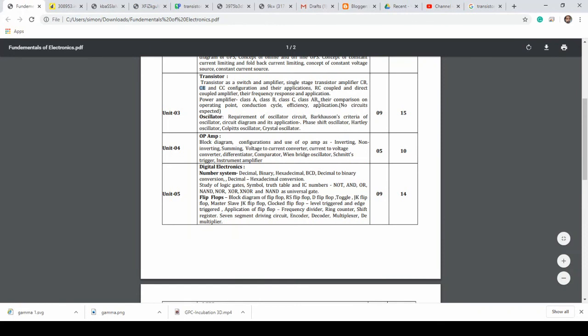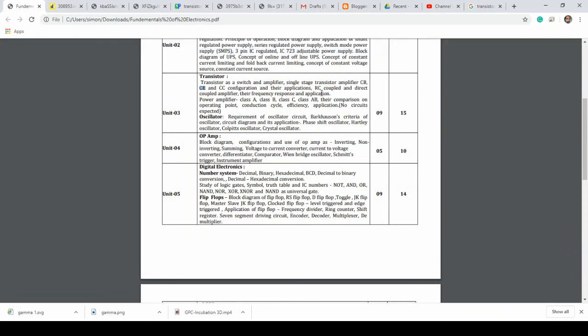And the next would be the frequency response. We're talking about the frequency response. At what frequency will the amplifier be able to give me desirable gain or desirable amplification in reference to dB? And we talked about the wide range of audio between 20 and 20,000 hertz. And for radio frequencies, for the particular frequency I'm going to operate at, the resonant frequency of the oscillator and the antenna working on that particular frequency to dissipate the maximum power, so that I can have the maximum range of transmission. So let's look at this in detail as we look at specific applications with transistor-based amplification in the next session or two.